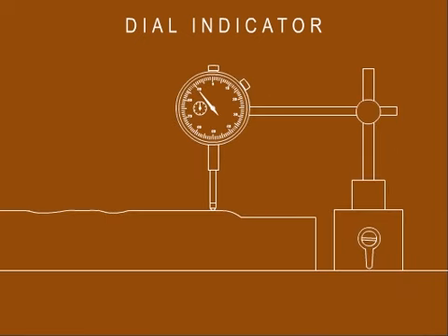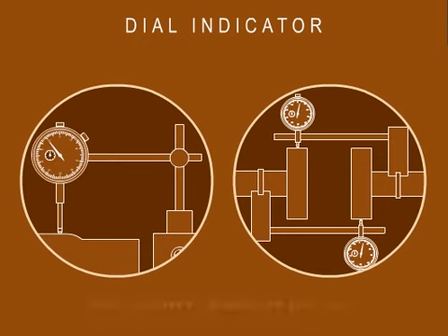In this example, a dial indicator can be used to determine the flatness of a part's surface. The indicator body is fixed relative to a reference surface and set to 0, with the plunger having sufficient travel to extend and retract to maintain contact with the part's surface, ensuring measurement. As the part resting on the same reference surface is moved to various locations to make measurements, the needle position varies from 0 and the change in value can be recorded. It is also used to check shaft alignment, run out, and soft foot.